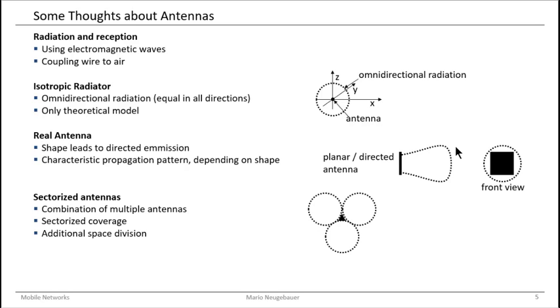And therefore, we take multiple antennas and direct them with 120 degrees difference in this circle here to form such a sectorized coverage of our area. And therewith we can get such a sectorization of our area, and these circles here symbolize the radiation which starts on such a planar antenna directed into a certain direction within this area.